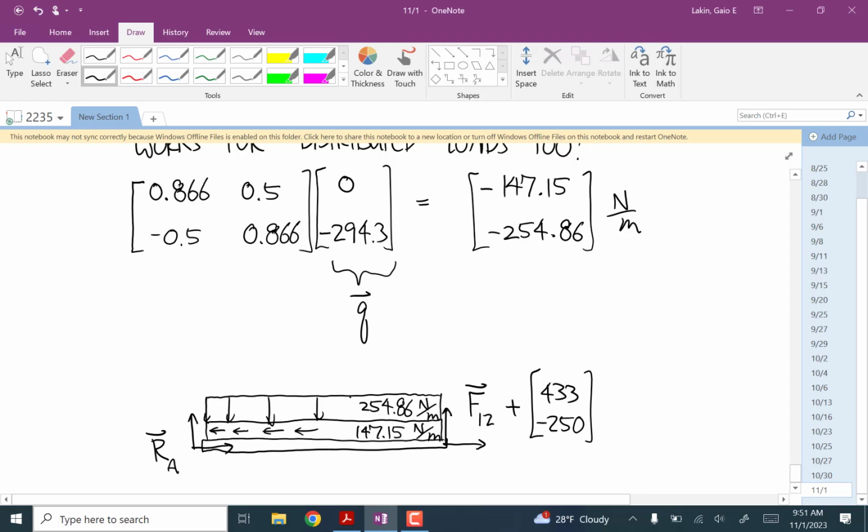It turns out dealing with the horizontal part is even easier because it doesn't produce a moment, but that's what we have to talk about next. And then we'll be able to calculate the internal loads in this beam that's in the world at an angle. Its orientation with gravity is different from what we're used to. We're going to have to rotate the reaction vectors as well. So we'll calculate the external loads, rotate those, rotate everything, and then we'll do an internal loads calculation. That's all we're doing, and you don't even have to know how to multiply matrices because your calculator does it for you.